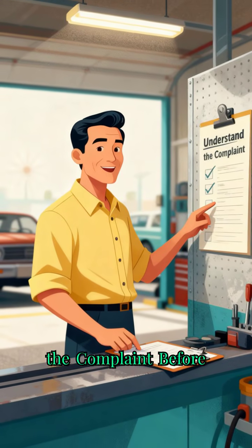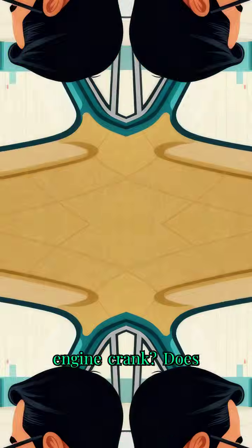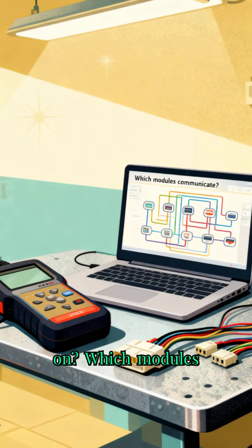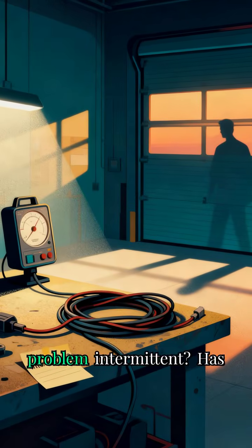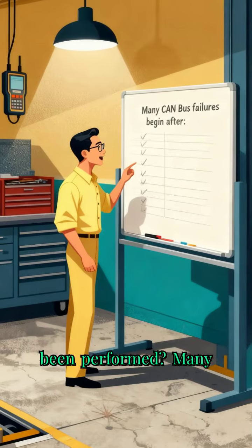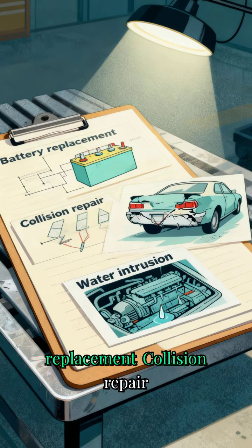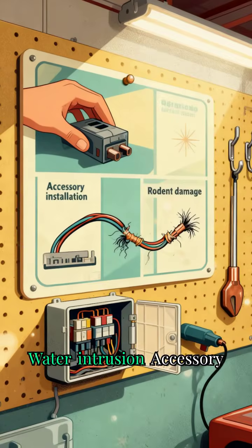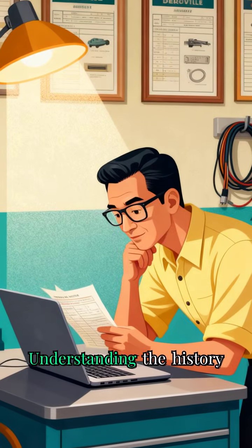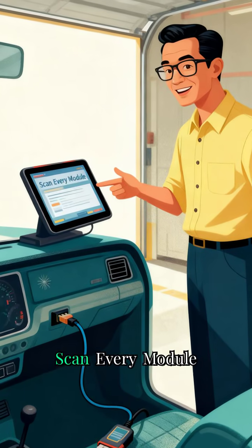Understand the complaint. Before touching the vehicle, ask: does the engine crank? Does it start? Which warning lights are on? Which modules communicate? Is the problem intermittent? Has any recent repair been performed? Many CAN bus failures begin after battery replacement, collision repair, water intrusion, accessory installation, or rodent damage. Understanding the history often saves hours of unnecessary testing.